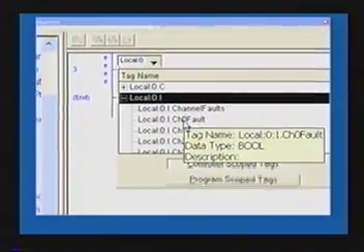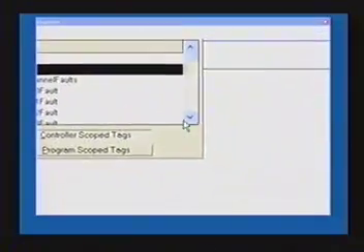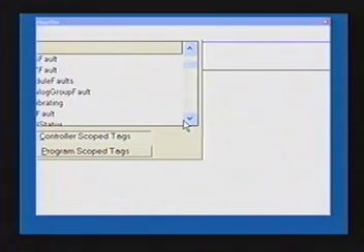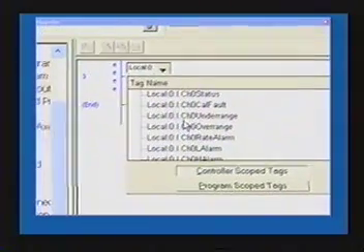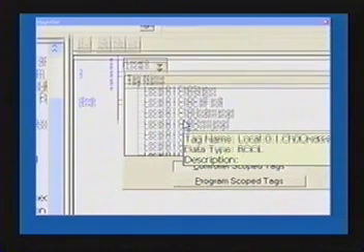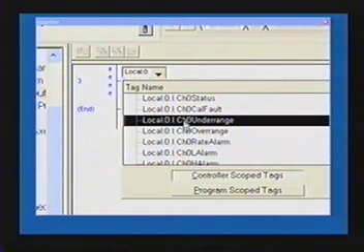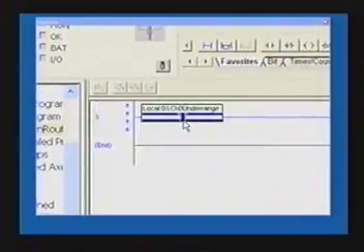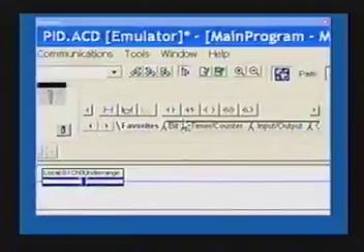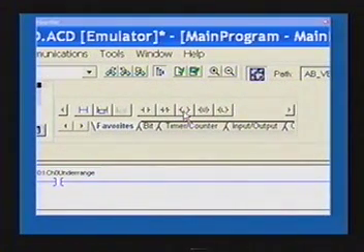So we got the channel faults, the actual fault conditions. Slide on down to, it gives us under range, over range. So under range is if it's below 4 milliamps, it'll be an under range situation. So let's go ahead and click on that. If that's true, that'll close, and we want to go ahead and latch that in. We'll say LIT